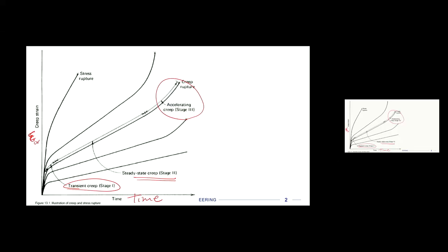Because it's a more complicated phenomenon involving time, stresses, and temperature, it's very hard to do testing at the conditions that you're trying to design for, because it would take a very long time. And you would have to know the working temperatures or replicate some temperature spectrum applied. And so there are three ways that our book talks about measuring creep. I'm just going to go through them. They all have advantages and disadvantages. But I just want you to know that there's no perfect way to measure and predict what creep behavior would be sometime in the future, or maybe at some other temperature or something like that.